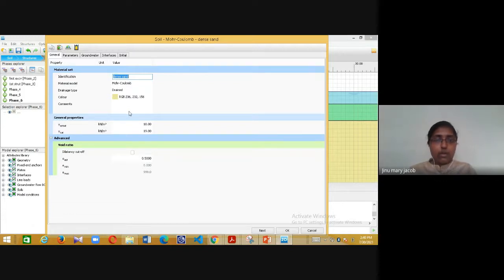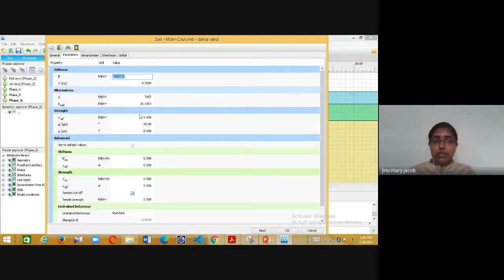There is another model called Hoek-Brown. Using that, since rock will have strength, using the RQD or strength properties, and also it will have joints, all such things come together, and from that Hoek-Brown analysis, C and phi will be determined and then used here. It will have both C and phi.